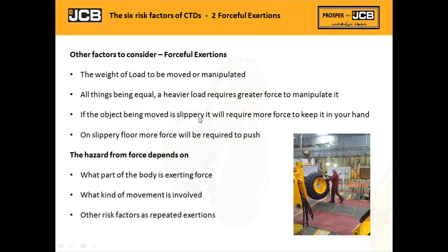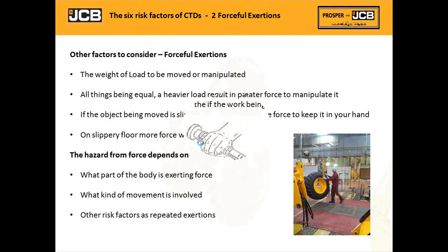If the object being moved is slippery, or if the floor is slippery and the person has to move the component or the weight, that means he will have to exert more force through his hand, and similarly on a slippery floor, more force will be required to push. The hazard from the force depends upon the part of body which is involved, what kind of movement is involved, and the repetition again we are talking about.